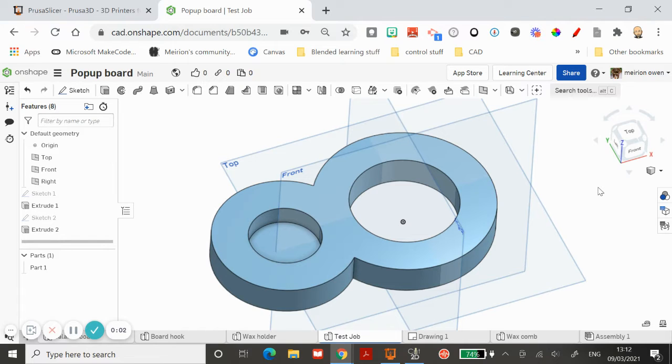So I'm going to run you through the process of moving from 3D CAD to a program called Cut2D that lets you set up machining parameters for the CNC router. And then in a separate QR code, you'll be able to see how we set up the post processor and how we export the job through another program called WinPCNC.